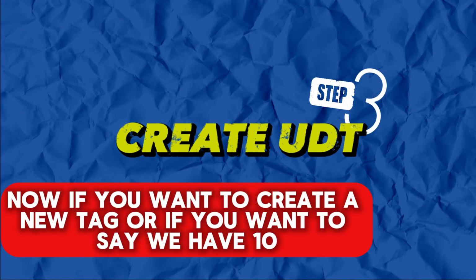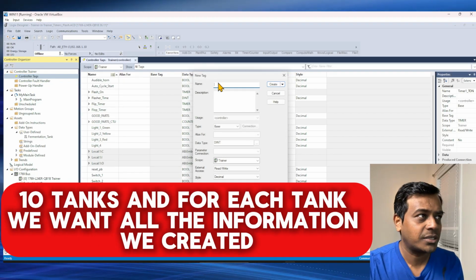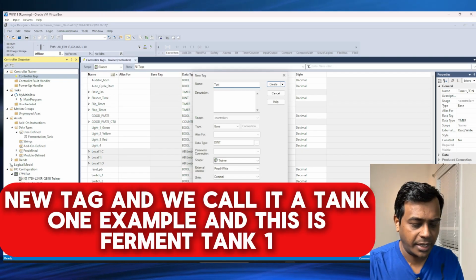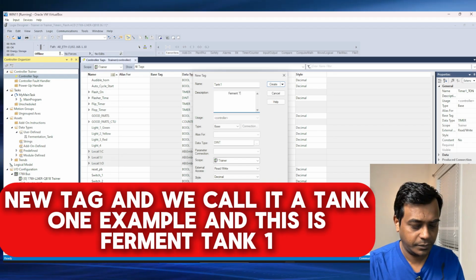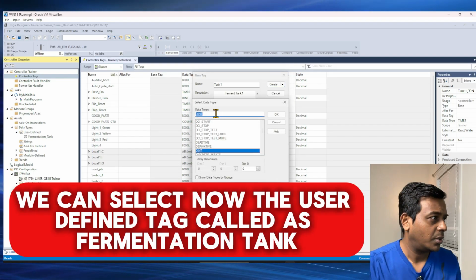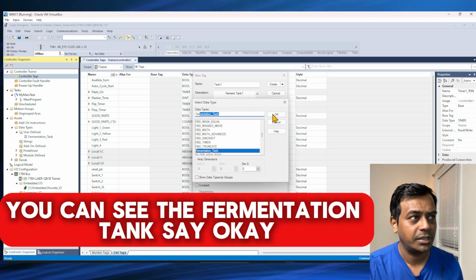Now if you want to create a new tag, or if you want to say we have 10 tanks, and for each tank we want all the information we created, we just go to controller tags, new tag, and we call it tank 1 example. And this is ferment tank 1. And in the data type window, we can now select the user defined tag called fermentation tank. You can see the fermentation tank, say okay.